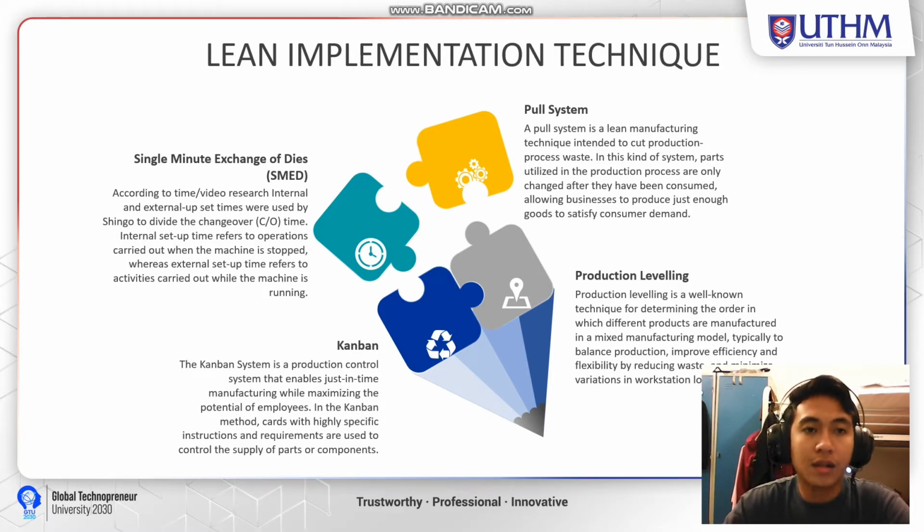In SMED, single minute exchange of die, according to time or video research, internal and external setup times were used by Shingo to divide the changeover time, CO time. The internal setup time refers to operations carried out when the machine is stopped, whereas external setup time refers to the activities carried out while the machine is running. So there are differences between external and internal setup times.